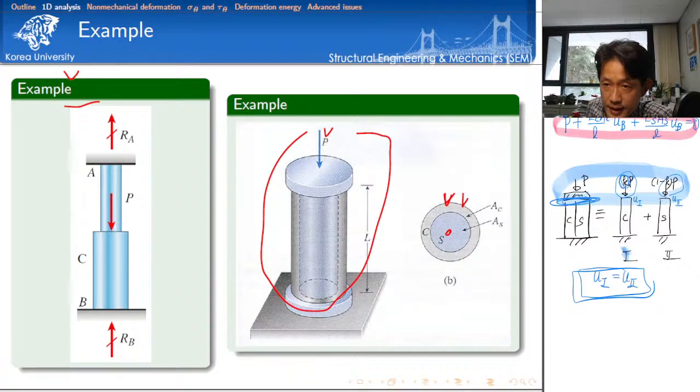Because this method is given in the textbook, I teach you, but this procedure is kind of obsolete. It's better to use the displacement compatibility directly to tackle the statically indeterminate structural systems. But the compliance method is still useful to derive some analytical form of expressions or simplification. Superposition principle, the principle of superposition, in Korean 중첩의 원리. This is very important to understand the analysis of linear elastic systems. So we will revisit the principle of superposition later.